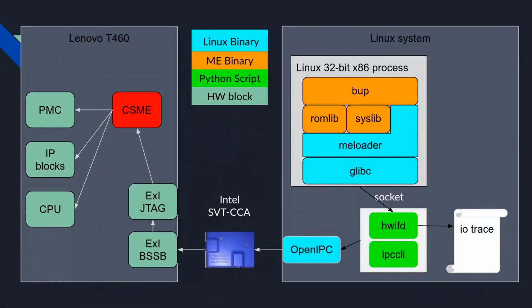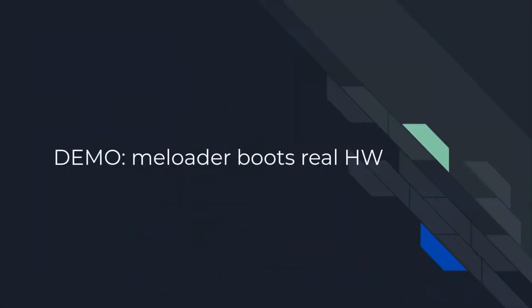I had the bring-up process from the ME running in a Linux process, sending whatever hardware accesses it was trying to do that are important for boot to the debugger, and then that was using an ME in real hardware that was halted to actually do the register accesses, and it worked. It actually booted the computer reliably.